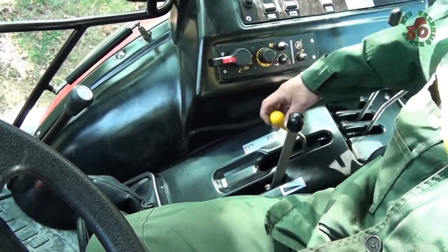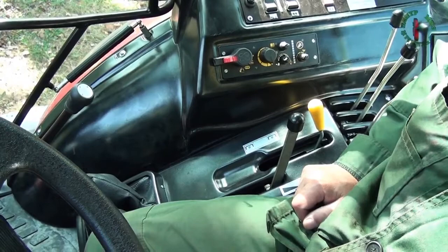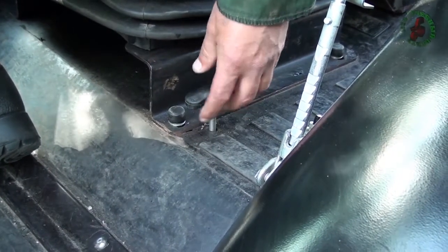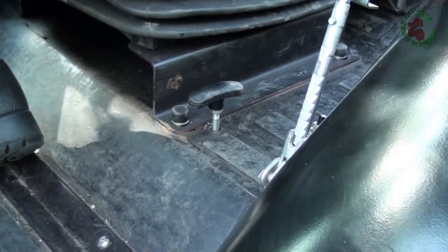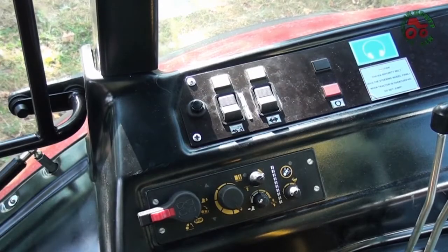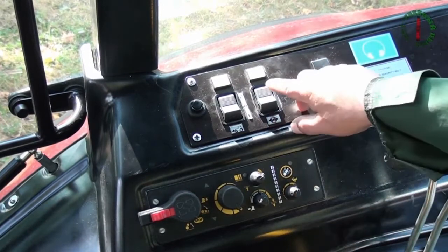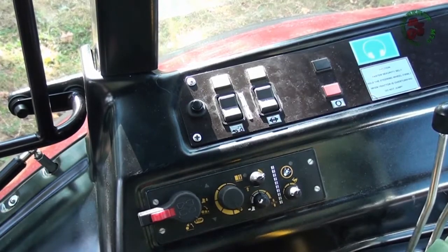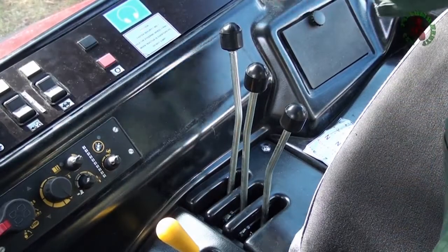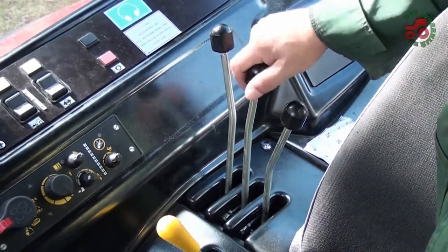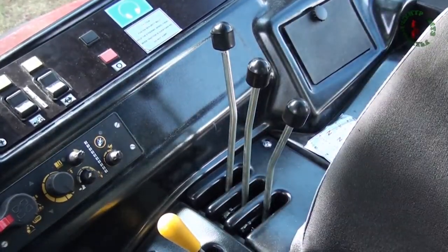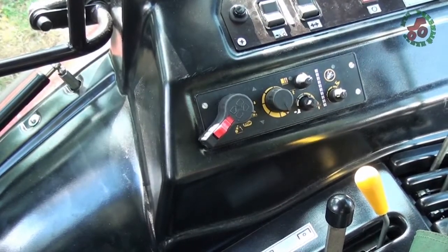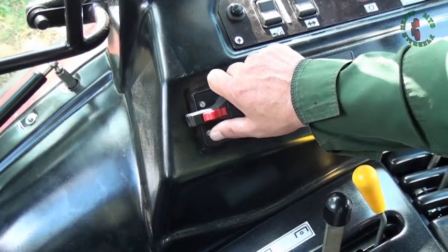Set the rear PTO control into the off position. Set the rear PTO drive lever into the position PTO drive off. Disengage the rear axle differential lock, the front drive axle drive and the front PTO, if installed. Set the handles of the hydraulic distributor system into the neutral position. Set the hydraulic lift linkers into the off position.